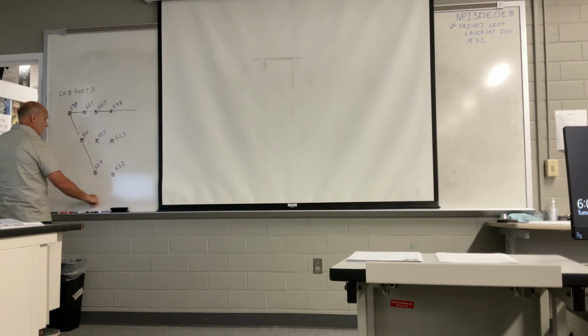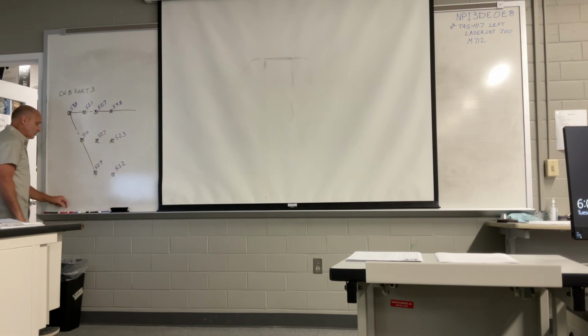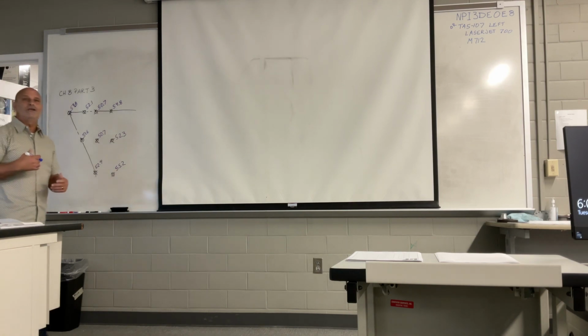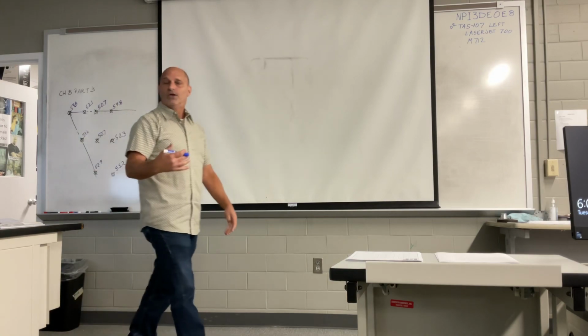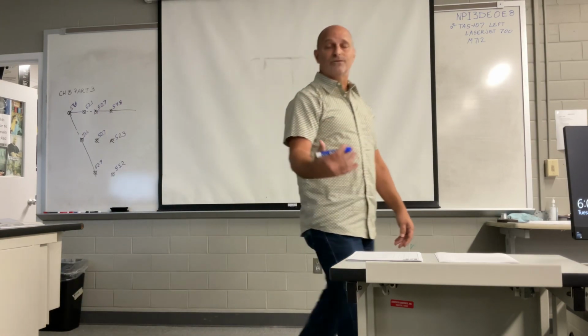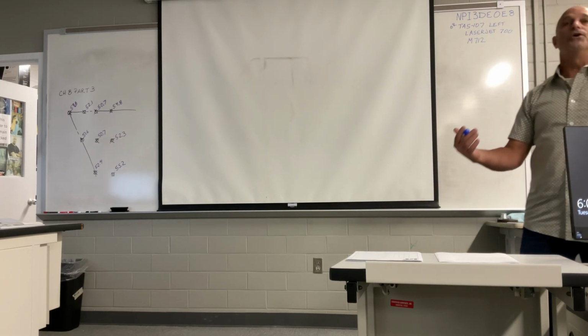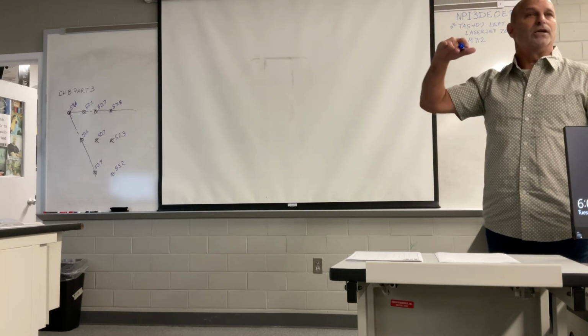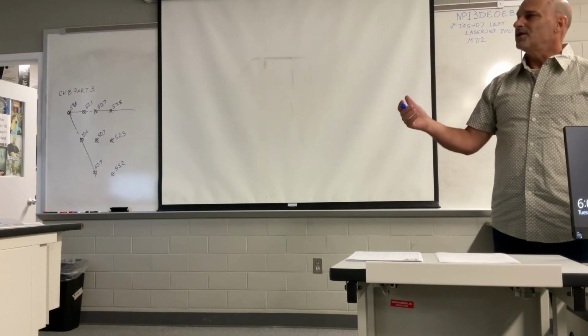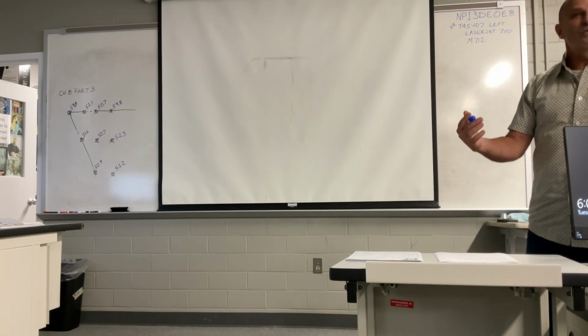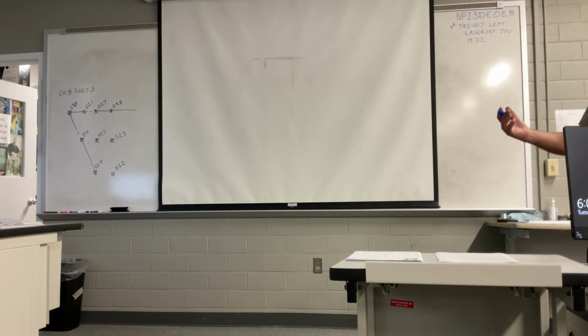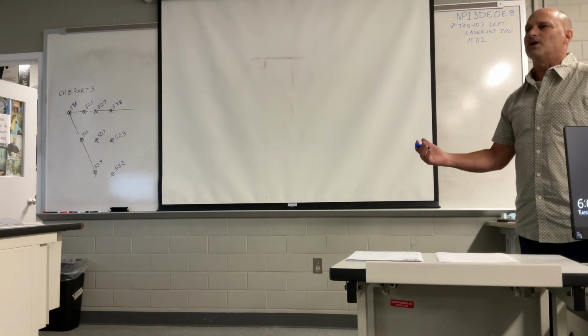The next step that you will be doing will be going point to point based on the elevations, not the rod shots. Whenever we do contours, we need to know what contour interval. If you're somewhere like in the mountains, if you look at a contour map for the mountains, it might be 100 feet of elevation change for every contour. Around here, being how flat we are in Southeast Texas, you're looking at probably a 6-inch or a 1-foot contour